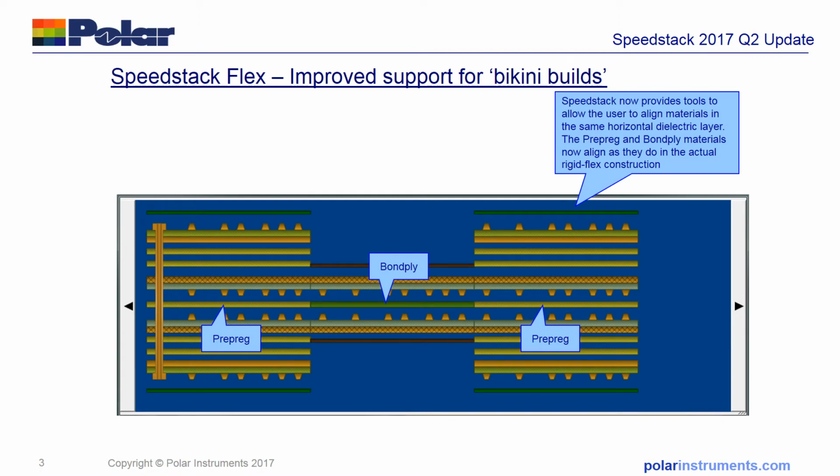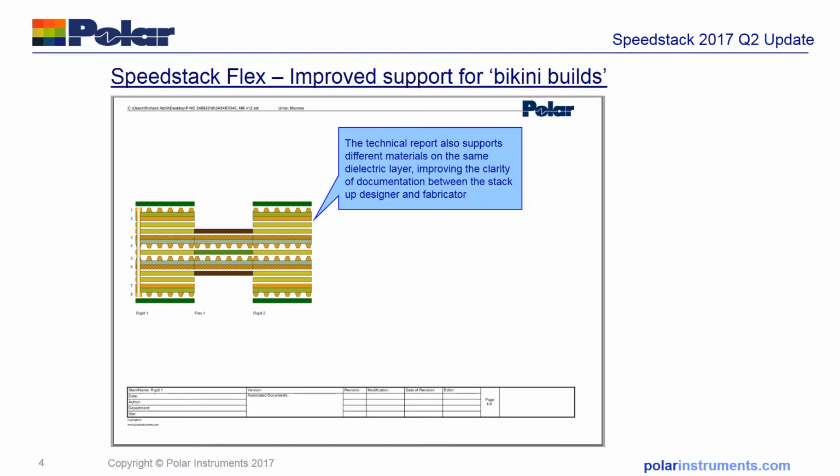This is the 2017 edition, and clearly here you can see the coverlay and no-flow prepregs are aligned, as are the bondply and no-flow prepregs on the inner layers. This is optional, and you can set this during the editing of the stackup. That information is carried through into the technical report, allowing you to show in the technical report a very accurate description of the stackup as it will appear in production.